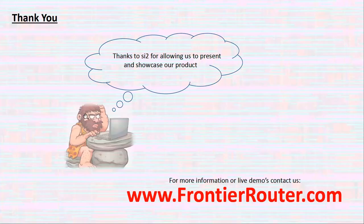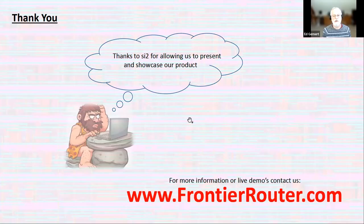What's the difference of this routing tool with the place and route tool? Is this for digital place and route only, or is it also handle analog? No, we're mostly focused on analog. We do some analog features like shielding. We're working on differential pair. They'll be coming up shortly. Matched and min length, multiple widths, multiple spacings. So it's for the analog. This is an analog router.